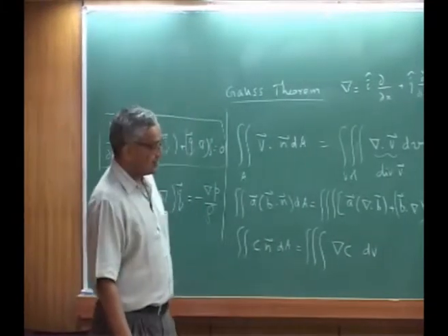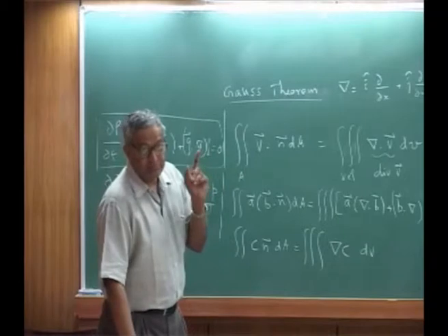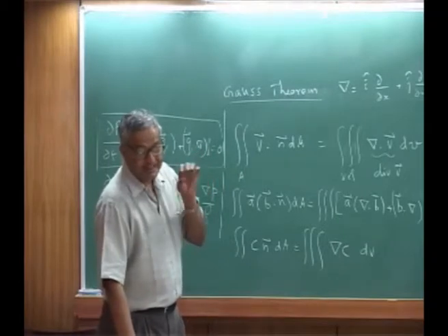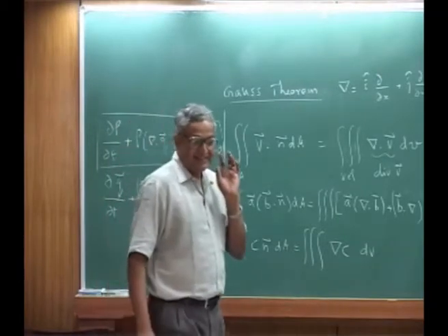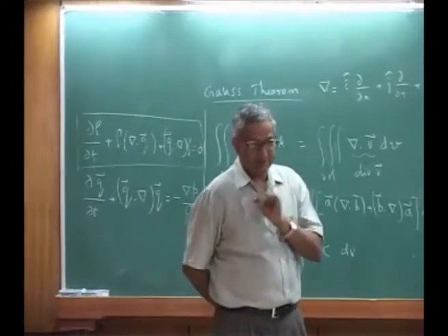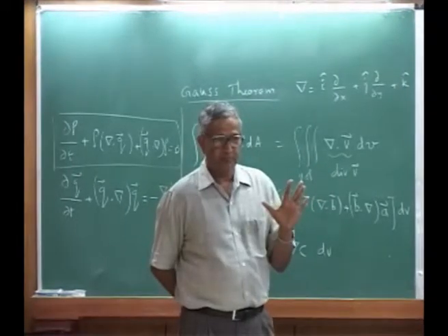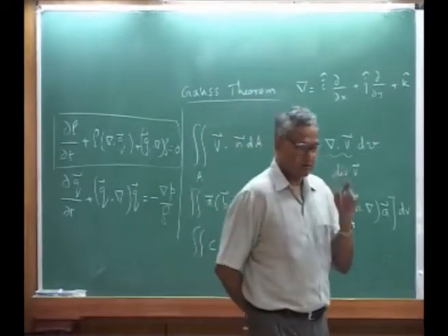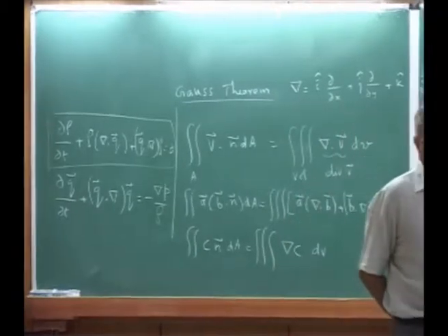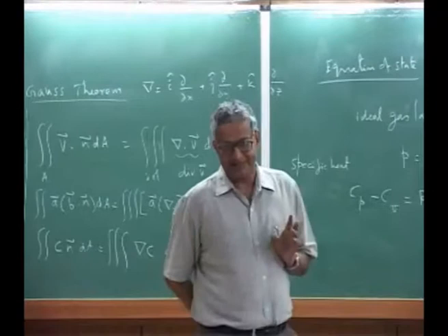Please understand what assumption we made. It is an isentropic flow. That means no heat is added, it is an adiabatic process, constant entropy, reversible. Usually this gets spoiled only when you have a strong shock, because at a shock there is local heating, and it gets disturbed.